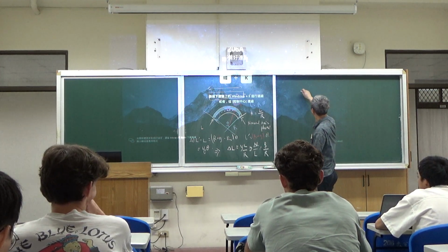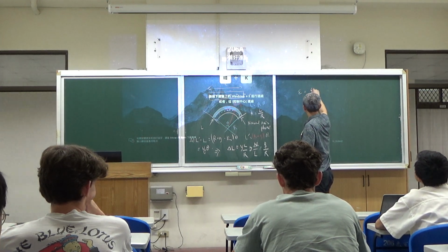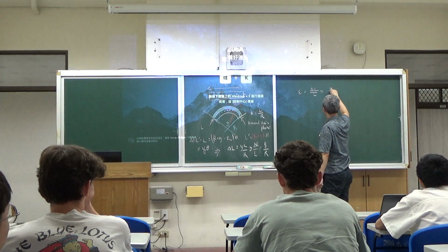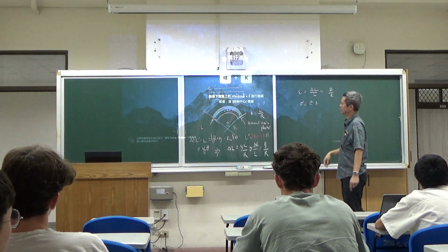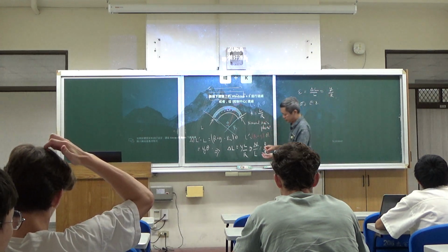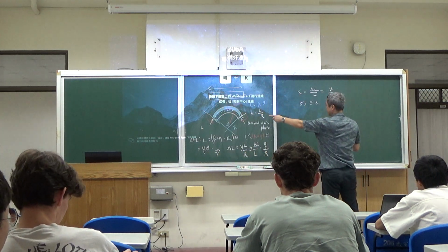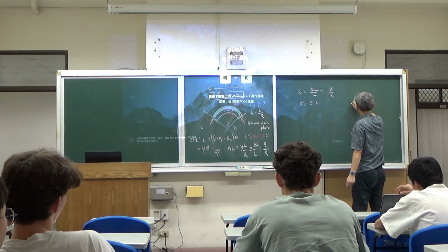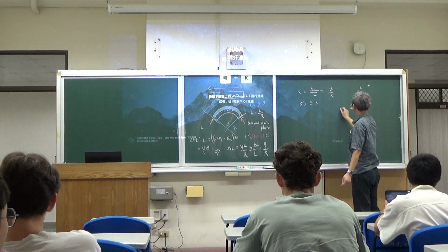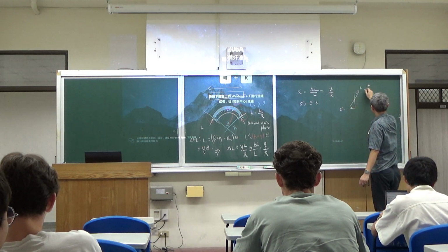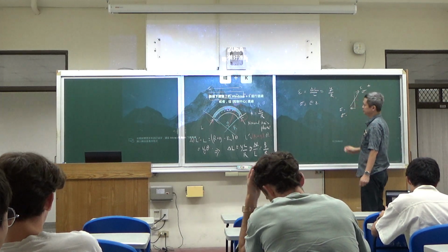So this is what you have for the strain. The strain is equal to delta L over L, which is equal to y over r. How about your stress? The stress is Young's modulus times the strain. How much is the total moment that is required to bend this? Over the sections, you can see this is in tensile strain, and this one is in compression. Likewise, the stress is also tension here and compressive there.